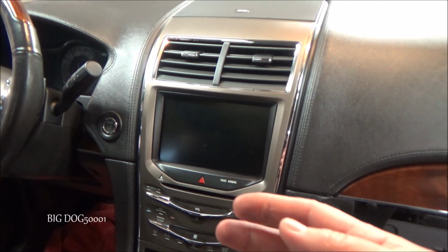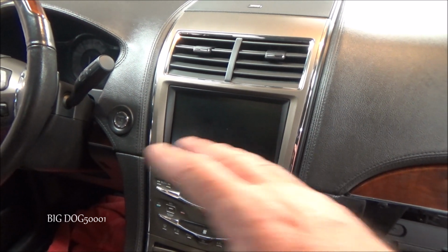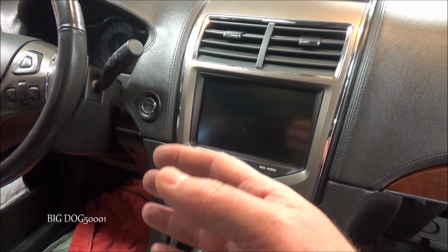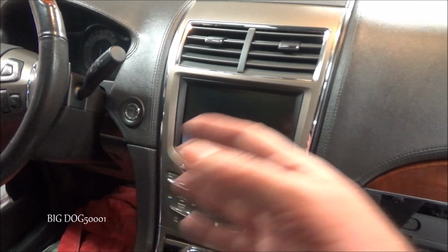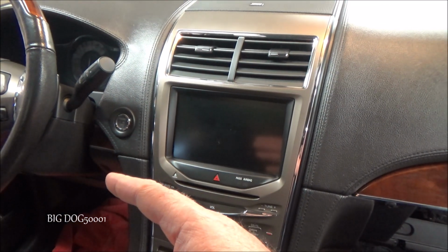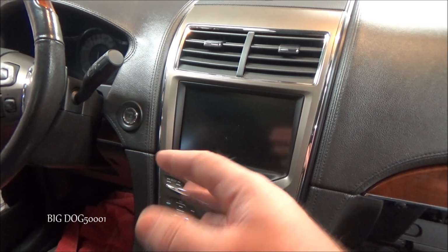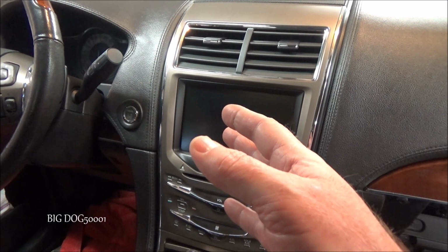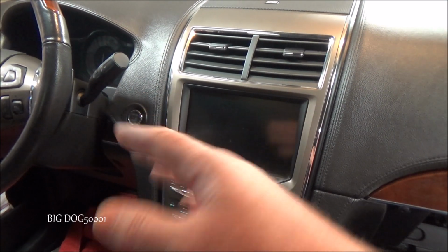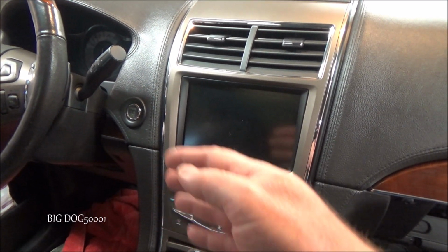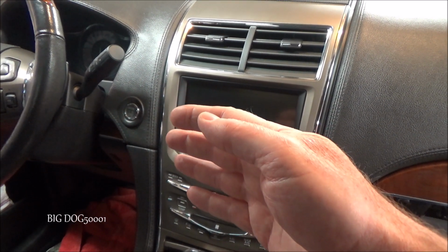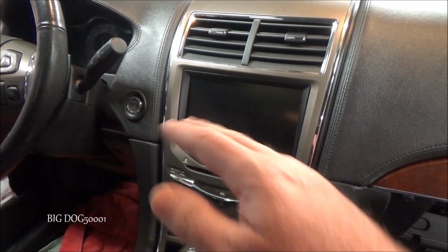When I think about those three things while dealing with the problem, I try to think about it logically. If it's summertime and the complaint is that when I'm running the AC, it's blowing cool on one side and a little warmer on the other, I'm typically going to look toward a possible refrigerant issue, because of my experience and because we're dealing with summertime and AC. I'm going to look toward an AC problem first. It might not be the case, but I'm going to be thinking about that more than other things.